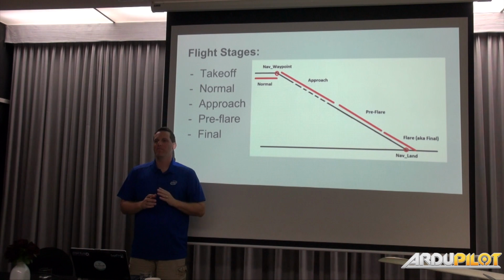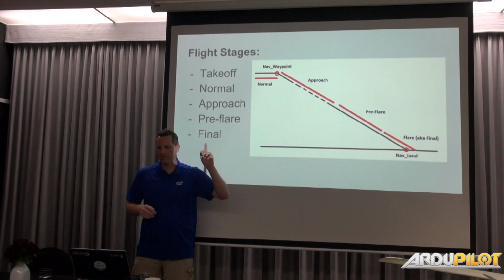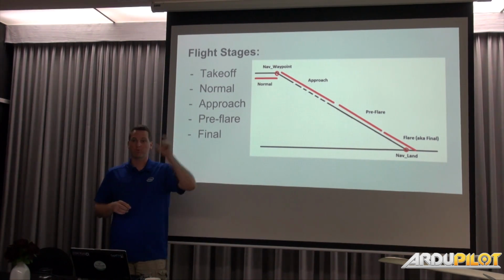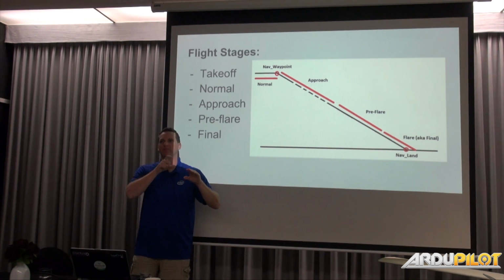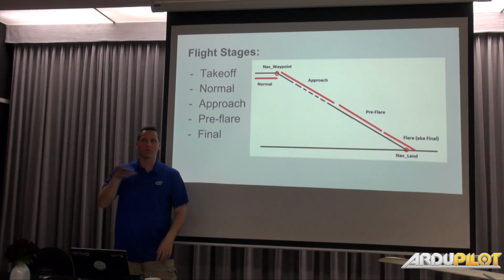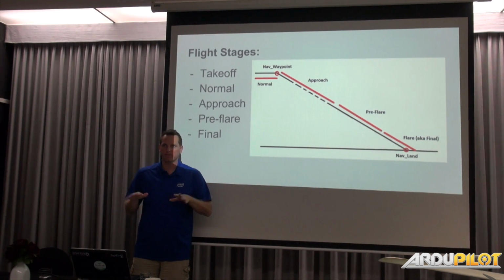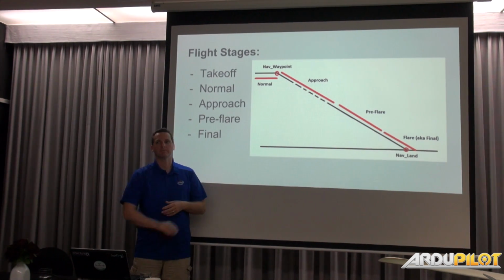And then that's just another threshold that you can optionally set, a lower airspeed just before. So you can set it before you're in a safe airspeed. You have a cruise airspeed, and then an approach airspeed, which slows down a bit, and then a pre-flare, you slow down more, and a flare, you're just hitting the ground. So at a flare, motor's off, you're still armed, but you're essentially disarmed. The motor's been cut off, and you're just basically gliding until you hit the ground.